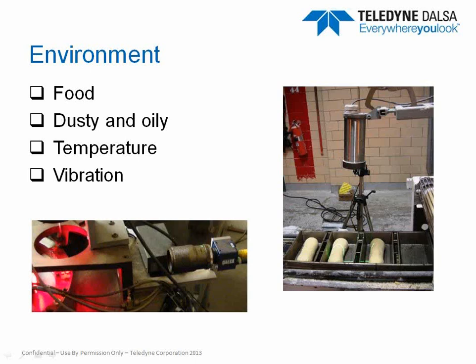Reason for that is in any kind of FDA food, if you're in the wet area, they wash all the equipment with a chlorinated mixture of water and other components that's very acid or chemical will eat away aluminum steel. So you would need things like stainless steel and plastic or rubber casings for the wires as well.